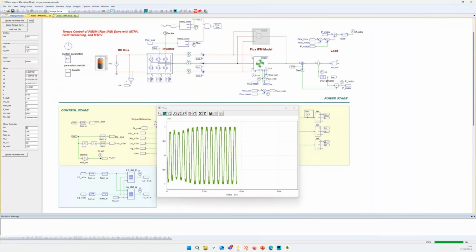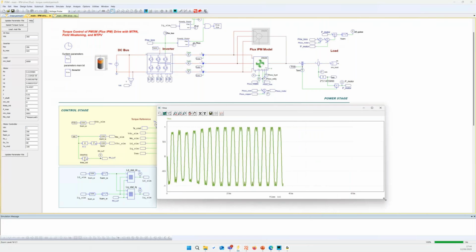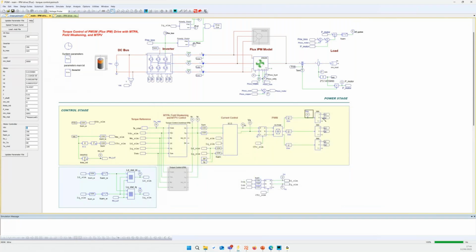And this is set by the V3 parameter here. So this is 1, which means the modulation should always be within plus minus 1. Otherwise, the system will be basically uncontrollable. Here I can see that it's within the range. I can see the nice space vector modulation signal I'm expecting, and I'm pretty sure the results I'm getting are good. So these are the tips for when you use the Flux models.